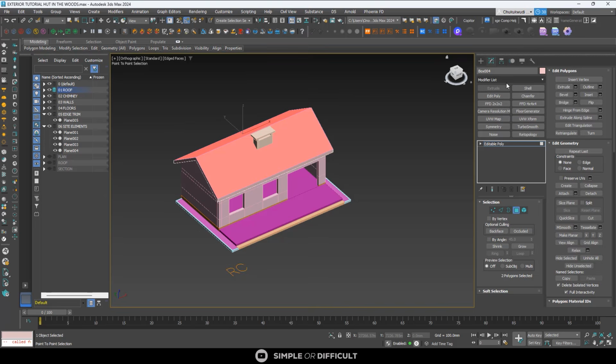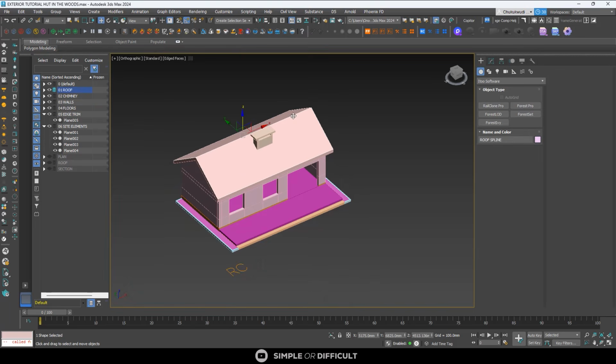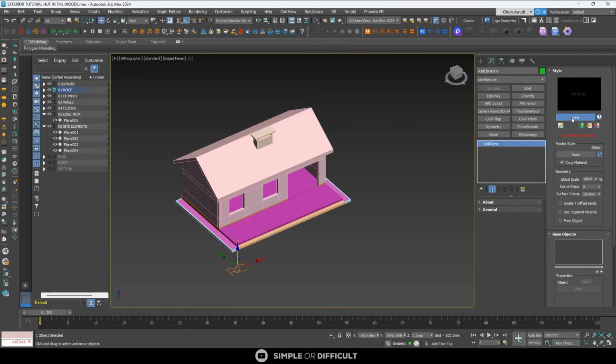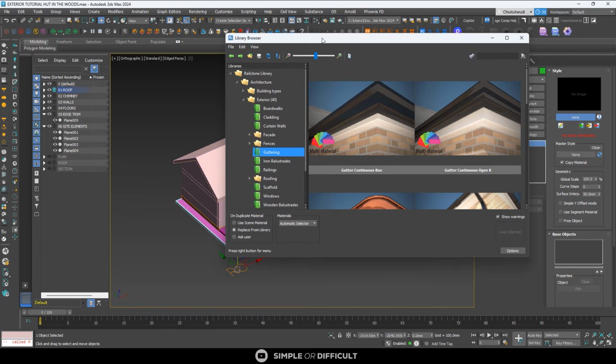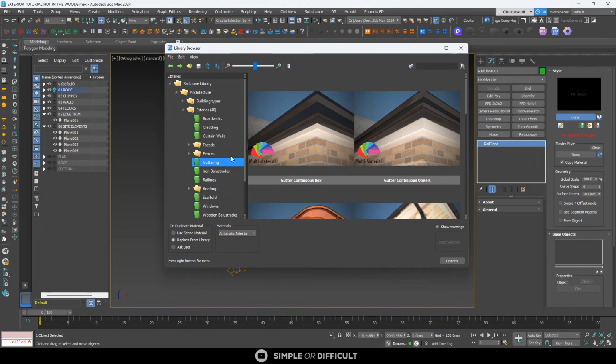So with that out of the way, I'm just going to come out of there. If I select this, you're going to see the spline that we need to create this RailClone roof. Okay, just follow this step exactly as I did, and you're going to get this result. So the RailClone Pro, I'm going to click on this. Okay, I'm going to open here, and I'm going to go into the library by clicking on None.